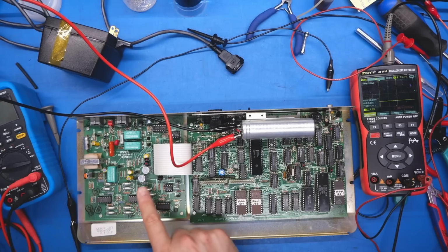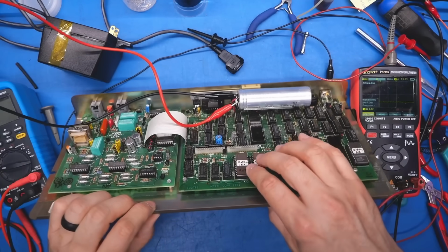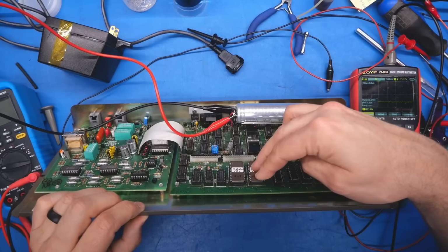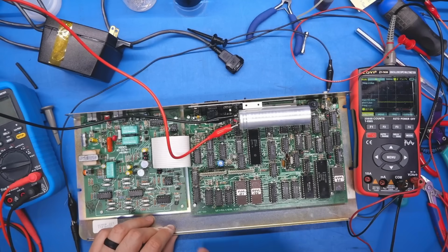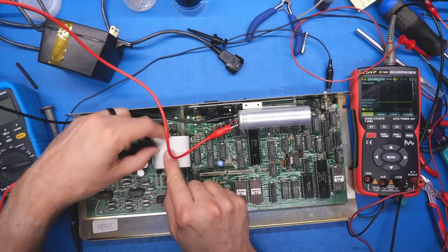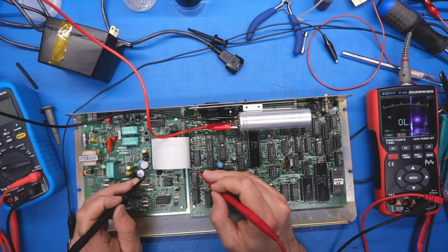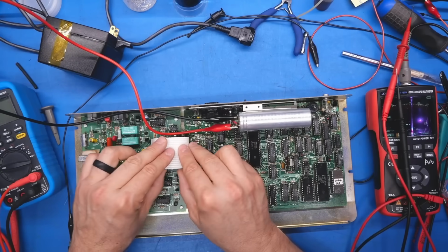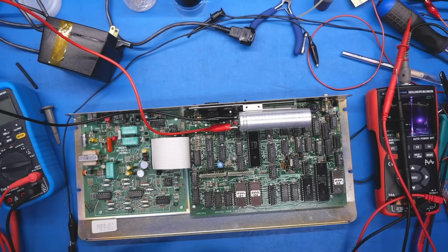So I turn the system off, turn it back on. Nothing's happening over here now. I'm just double checking I didn't bend any pins when I put these back in. And I didn't, because I had these out to dump them. I did unplug the modem. So I suppose a good thing to do is check continuity between each of these pins going to the modem board. But one thing I can say for sure is when I unplugged and plugged this back in, all of the pins are making their way between these two boards.